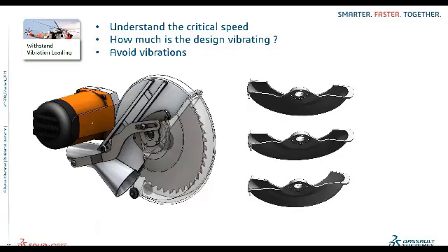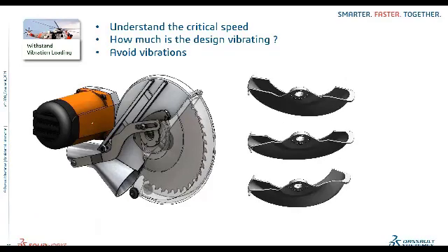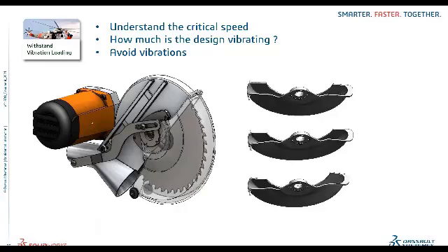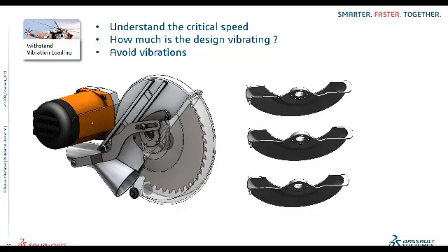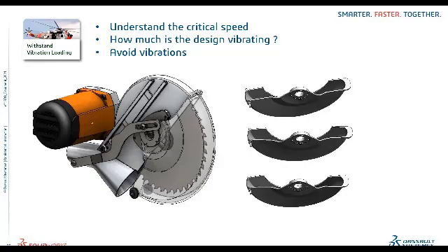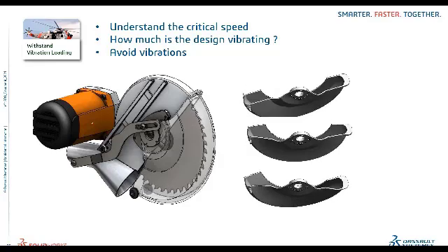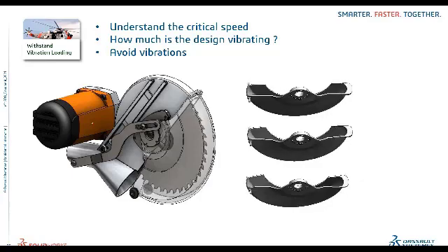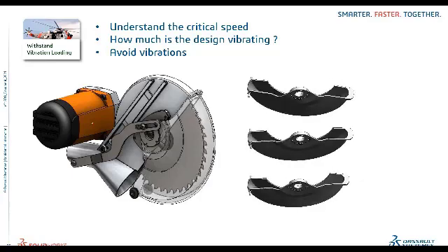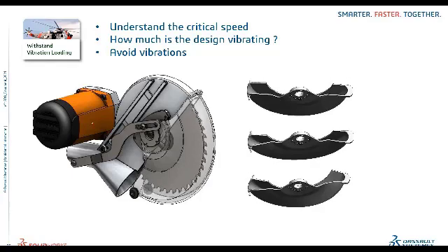And then the vibration loadings. So our solver supports the entire range of vibrations, as well as dynamic loads like time history, random vibrations, shock vibrations, and harmonic vibrations. We need to understand its mode shapes and natural frequencies before we take our product into the dynamic loads approach.